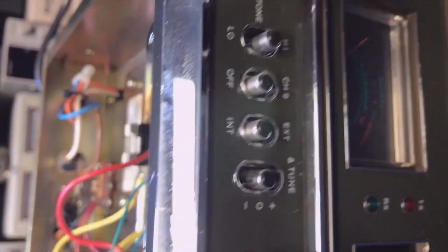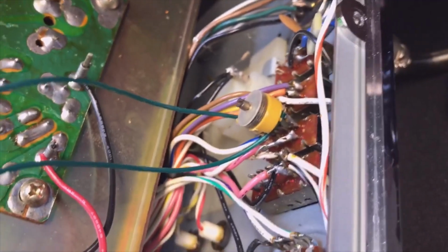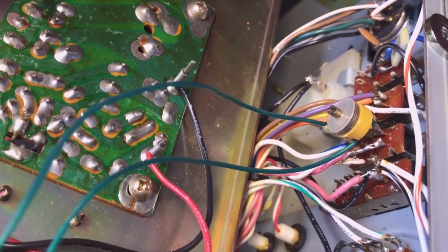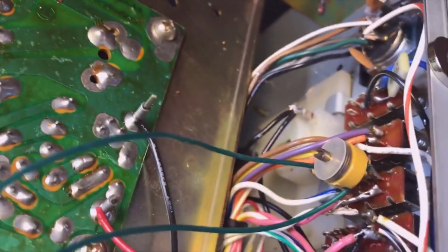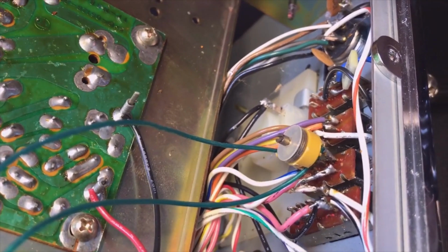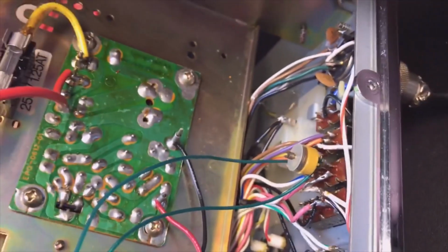So this is a perfect switch for this. We take out the wires and connect them as we want. The switch either short circuits this extra trimmer, or adds the trimmer in series. Now we need to put it on the right frequency.